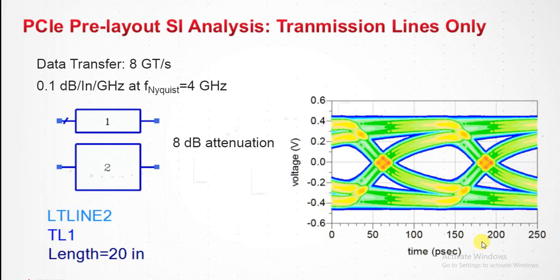And here is a case where loss might be your friend. Since the eye diagram is showing a little loss, the eye is a little closed, where the top and bottom are a little blocked off. That means where the crosstalk would happen, it would be masked by the loss here. And we'll see that in the next few slides.